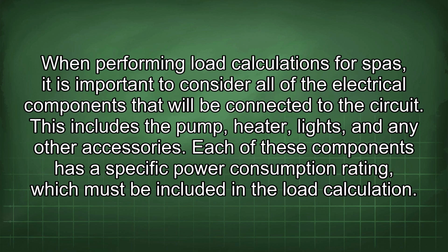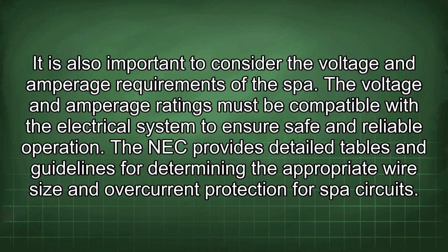When performing load calculations for SPAs, it is important to consider all of the electrical components that will be connected to the circuit. This includes the pump, heater, lights, and any other accessories. Each of these components has a specific power consumption rating, which must be included in the load calculation. It is also important to consider the voltage and amperage requirements of the SPA. The voltage and amperage ratings must be compatible with the electrical system to ensure safe and reliable operation.